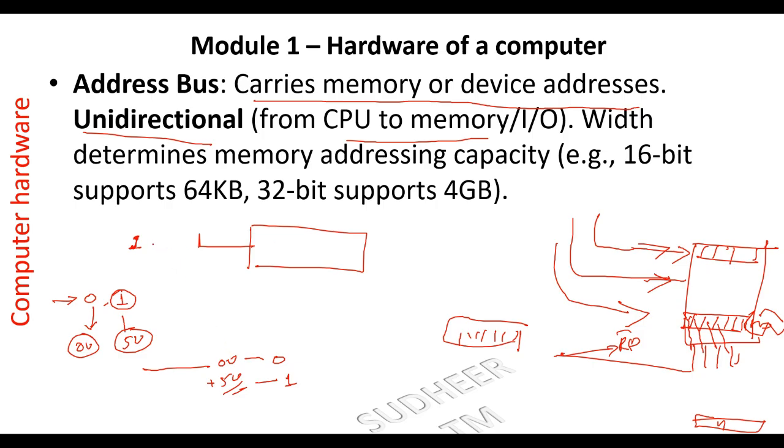Now my memory has only one address line. With one address line, how many memory locations can I handle within this memory chip? I am calling the memory unit's address line A0, the 0th line. As I mentioned, it can be at 0 or at 1. If I make that line 0 volts, I can select the first memory location. If that address line is at logic 1, or 5 volts, I can differentiate it to another memory location, the second memory location.